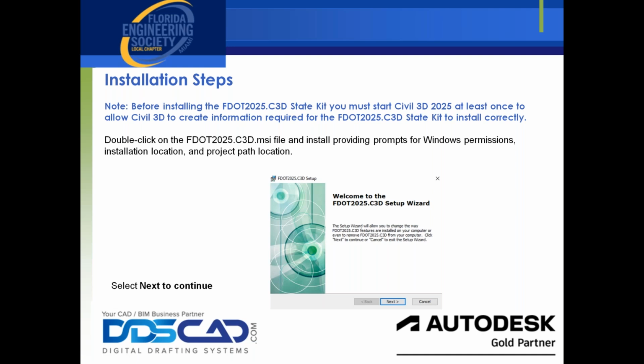Now, another rule. You must start Civil 3D 2025, or whatever version of Civil 3D you're installing the state kit on, at least one time prior to installing the state kit. You have to start it, let it run through the install and the startup process, get to the command line, and then you simply quit Civil 3D. Then you can start the installation process for the state kit, because we need certain files and folders to be in place before the FDOT state kit can be installed correctly.